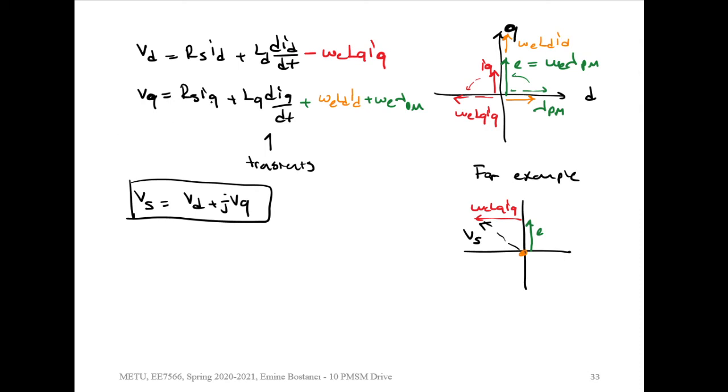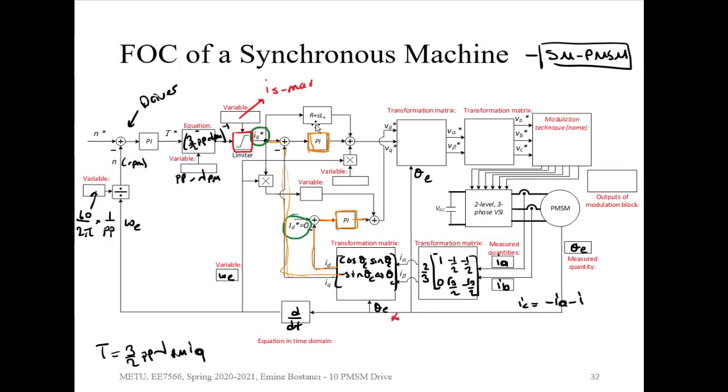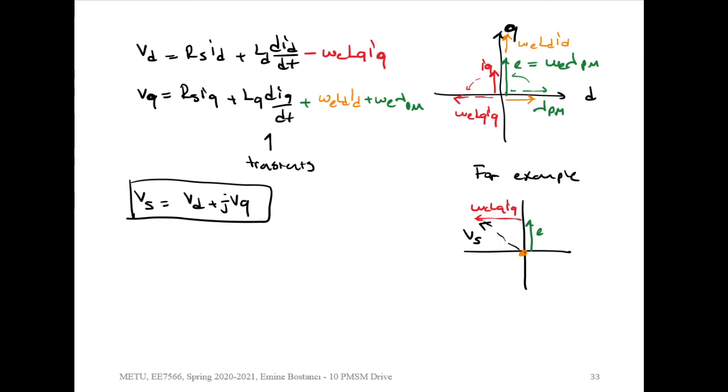So this is going to be my components. Now in the control loops, I'm just going to add the resistance and the transient term. You know that ID, IQ are DC values, so this derivative is going to be 0 at steady state. So I'm just helping the voltage calculations, because this is going to give me the voltage rating at the output. Therefore RS plus S LQ is for this first part, which is written in black.